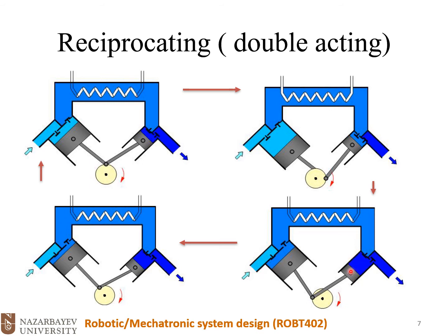Now the second cylinder will come into effect and will compress the air, and finally will exhaust the air to the output. So we go through 4 stages from the first cylinder to the second cylinder, and also absorbing the heat here and dropping the temperature between these 2 stages to achieve higher pressure.